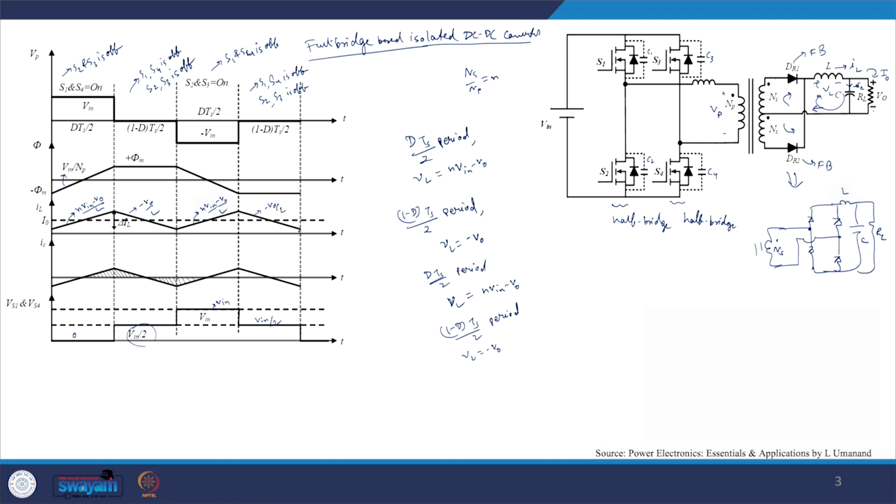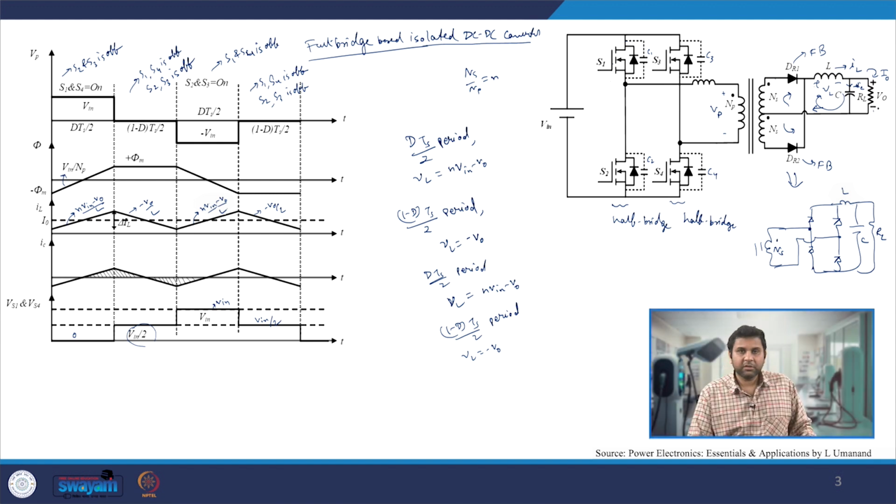So we will see falling inductor current, and the constant average value will be going through the resistance, while the ripple value will be flowing through the capacitance. So this is how we will get this particular analysis.